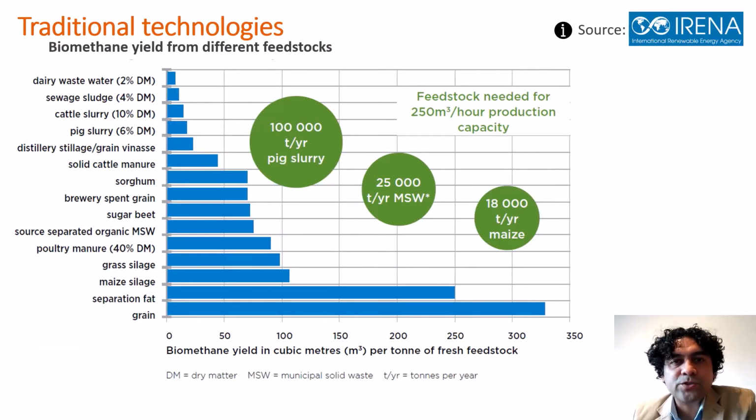For biogas production, biomass feedstock can be a concentrated and diluted liquid, solid, or slurries. It includes animal byproducts such as manure, agricultural byproducts such as straw, biowaste from households, industrial and commercial waste from markets and restaurants, sewage sludge from wastewater treatment plants, among others. Wood biomass has a high content of lignin and it is not suitable for anaerobic digestion. As shown in this slide, different feedstocks have different biogas yields and cause different methane contents.